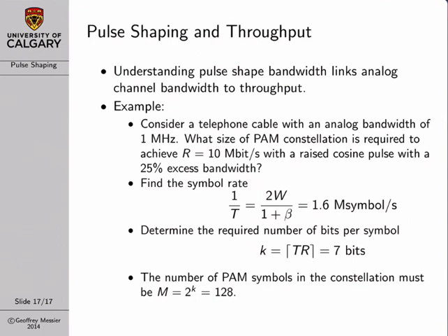And so the first problem faced by the communication engineer is what kind of modulation scheme you need to use in order to satisfy your throughput. We know as we increase the number of signals in our modulation symbol set, we can transmit more bits per symbol and increase our throughput. However, we don't want to use too many symbols because as our signal vector diagram gets more crowded, the chances of bit error rate increase. And so we want to have just the right number of symbols in our symbol set.